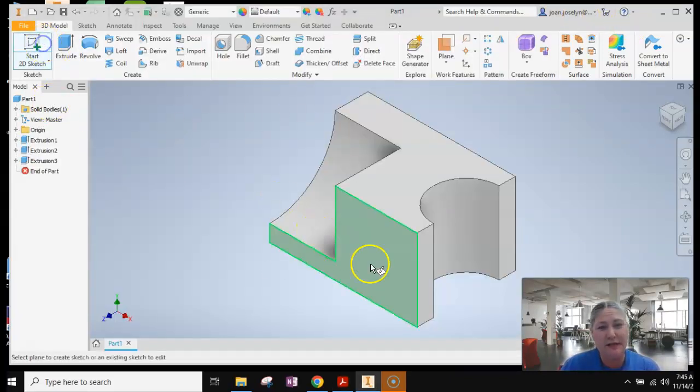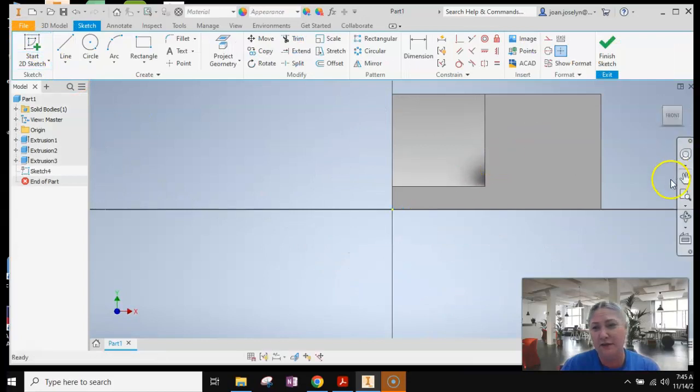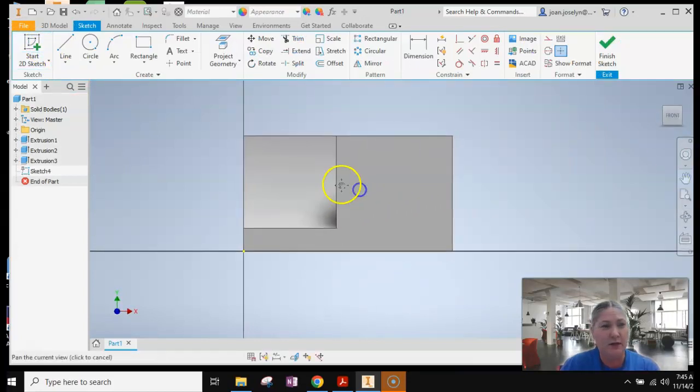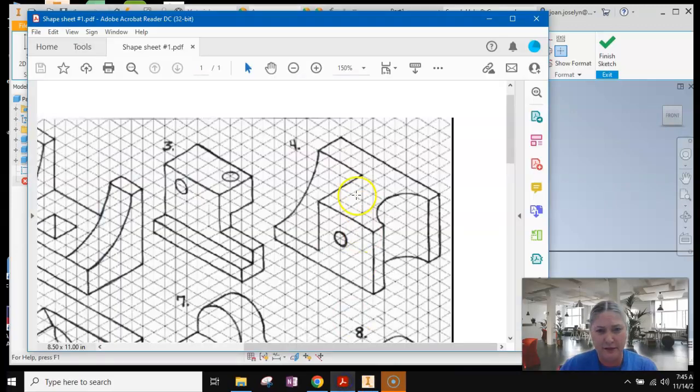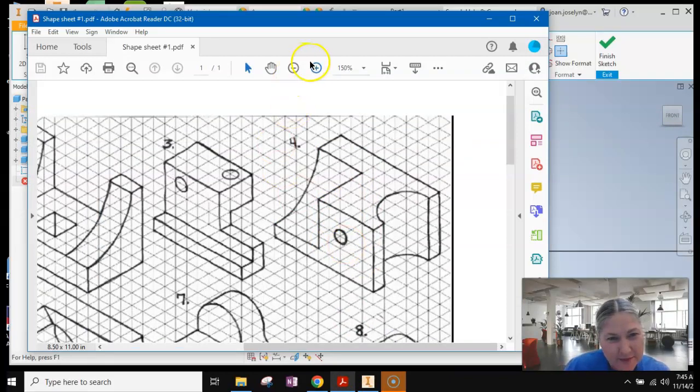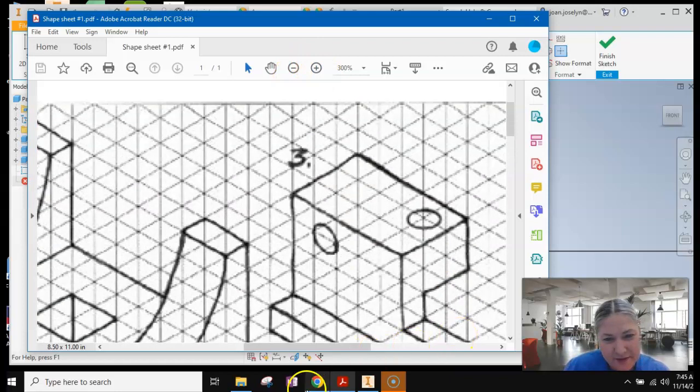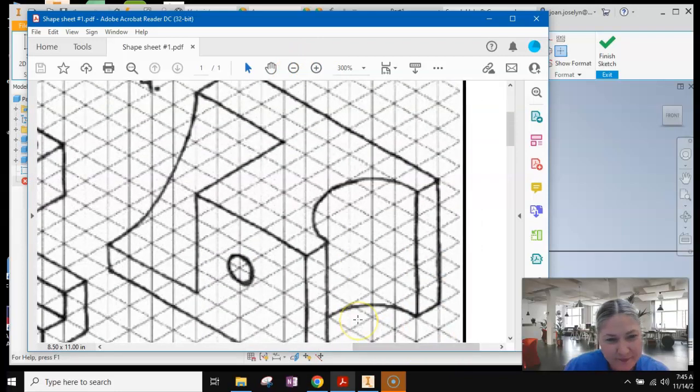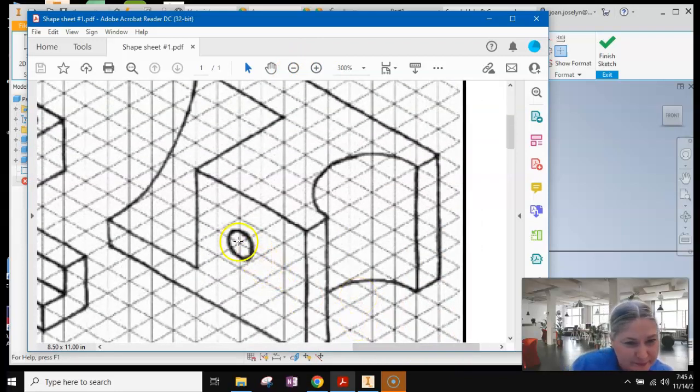All right, new sketch on the front face here. I'm going to drag it over, and we'll use the circle tool 1 more time. You could use the hole tool, but it's not necessary. We're just going to drag it anywhere. It looked like it was 1 box wide, but I'm just going to go back and check. Yeah, it's in the center, but you can see how it's about a half on either side. Is that right? Get that closer. Yeah, looks like it's about 1 box wide.